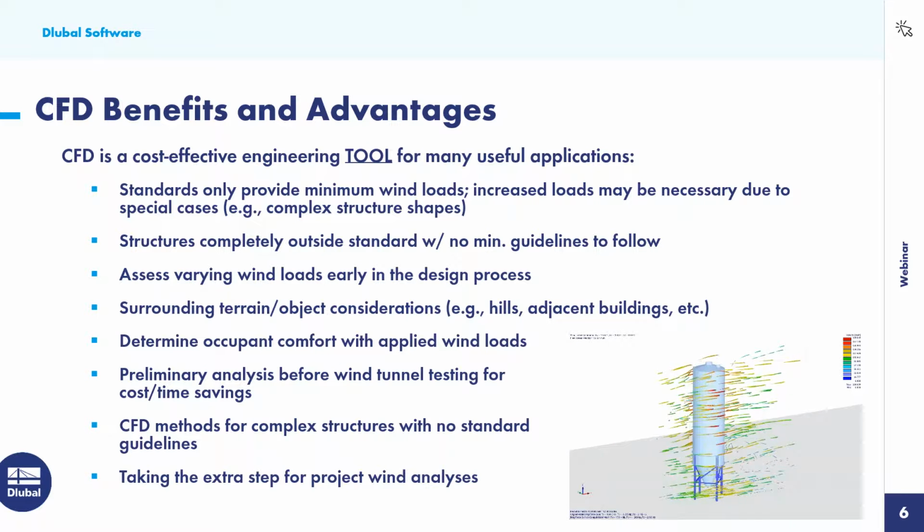Now, ultimately, if a true wind tunnel test does need to be carried out, you can imagine the cost and time savings that we could have if we were to initially run the CFD analysis to adjust our design, whether it's under design or over design, before we're spending the time and the money to do so with that true wind tunnel test. So overall, CFD methods should be used for complex structures with no standard guidelines.